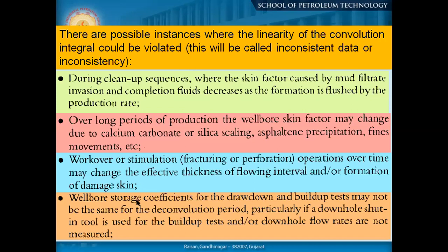Wellbore storage coefficient for a drawdown and a build-up test may not be the same for the deconvolution period, because the two cases are different. Why? Because when we are removing crude oil or any sort of fluid from the wellbore, the effect on the pressure, and when we are closing it in, the two things are different.